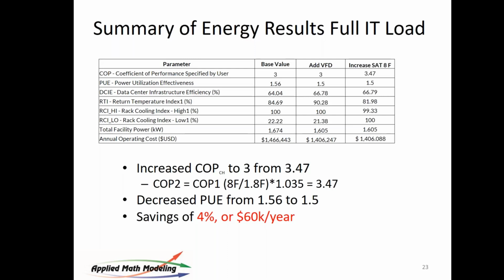Can you explain how to do the same procedure for raised floor design? This was a raised floor design. So they're all the same. I think you might have meant non-raised floor. The methodology is exactly the same. You lay it out the same way. You first try to get your air balance in position. Once you've got your air balance in position using the new VFD controls, then go ahead and raise your supply air temp and try to move it up a little bit.